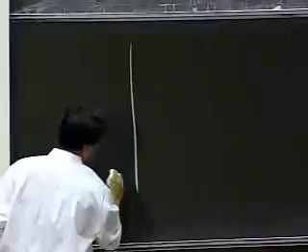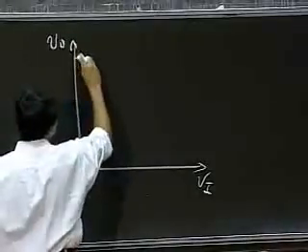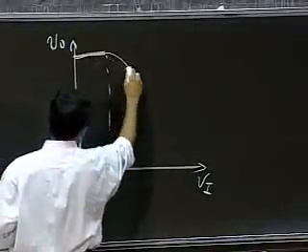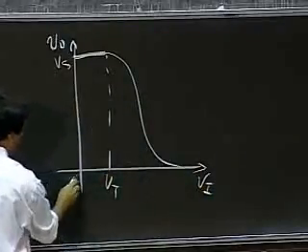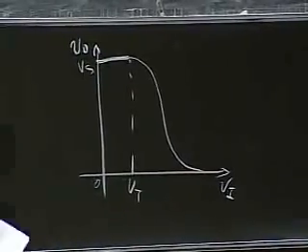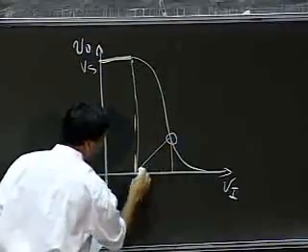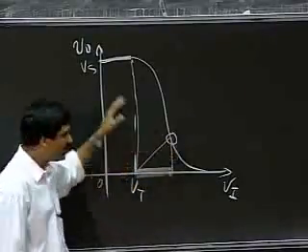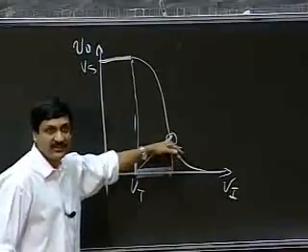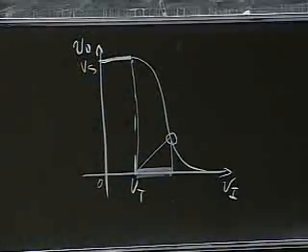How do I make my amplifier operate in that region? The answer is pretty simple. Let me drive the intuition again using a graph, V naught. So this is a graph, and I showed you that was my valid region here. So take a 45-degree line, find out where it intersects the transfer function, then this is the valid region here, VT through that function that we developed.